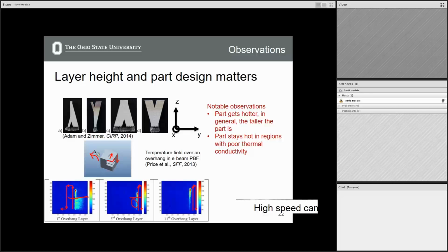Yeah, but think of this almost, and we'll get into how we specify this, but we'll consider this to be a Neumann boundary condition in terms of no heat flow into that. As a simplification, it's not purely the case. You can imagine that some heat flows into the powder, but it's pretty small.